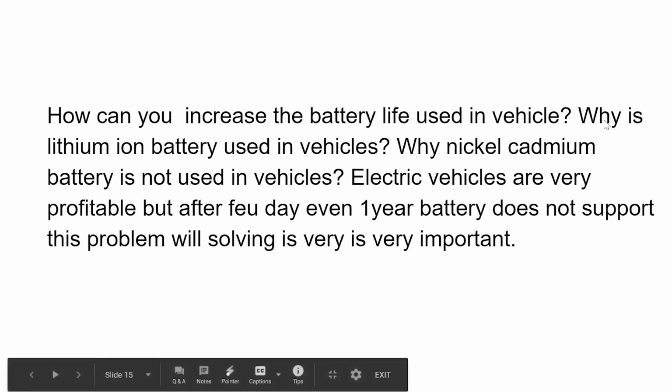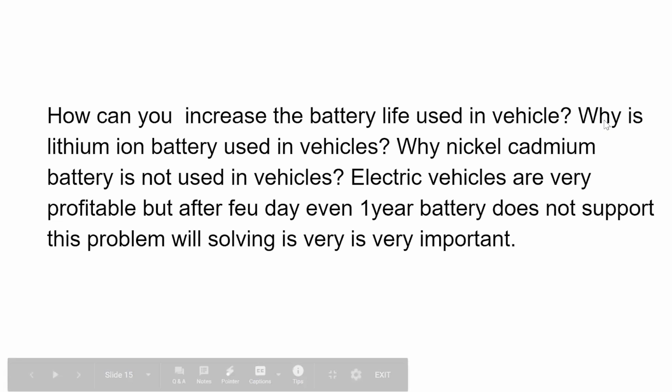The battery life of the vehicle can be increased by having an intelligent battery management system. So you have a complete set of software that looks at all the cell voltages in the vehicle, and it tries to determine whether it is reaching its operational limits or not. And then the control strategy that runs the vehicle takes that into account, and they never exceed the battery's limits. Using these sorts of methods, you can increase the battery life of the vehicle.